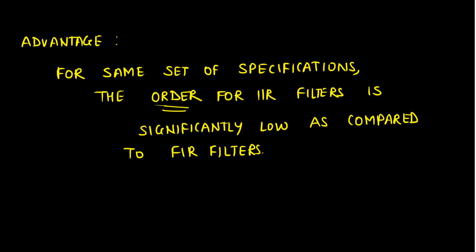So if we have a situation in which there is no need of causality or stability or a linear phase, then we can very well go for IIR filters, as we require a significantly lower value of order for achieving the same set of specifications.